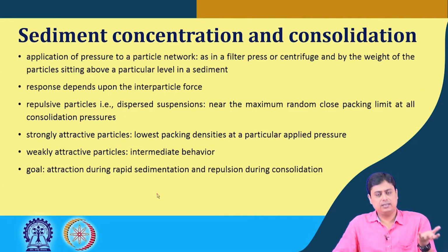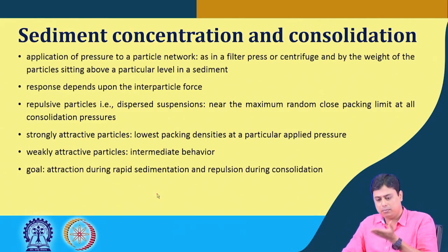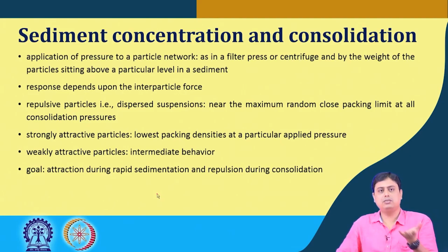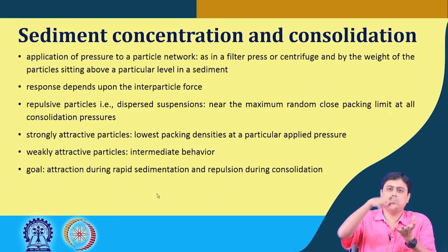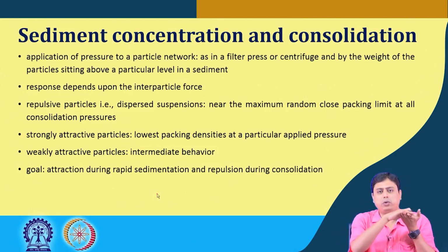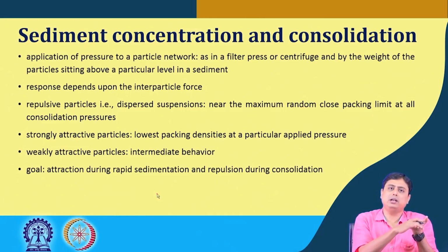If the particles are repulsive in nature, we have the near maximum random dense packing at all consolidation pressures. That means we now try to consolidate the sediment. For that we apply pressure either by centrifuge or by filter press or by putting some weight on the top of the sediment layer.